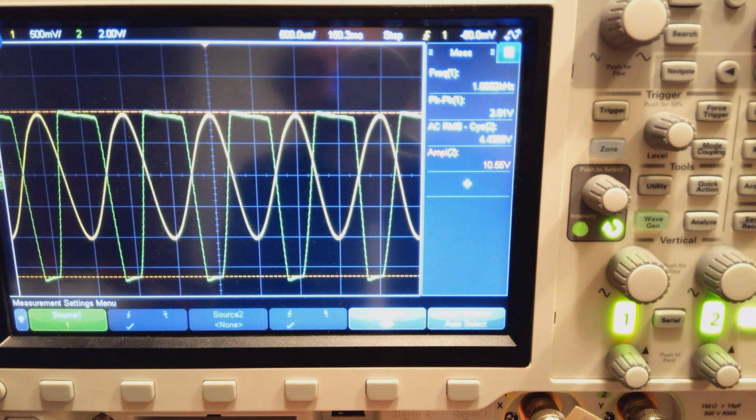If you listen to this on a loudspeaker, you would hear a lot of distortion at this point in time. As you'll learn with Fourier analysis, the sine wave is a single frequency at 1 kilohertz, but now that output is almost like a square wave, and it would have odd harmonics. By overdriving the amplifier here, you've created new frequencies which weren't there in the original signal. We call that total harmonic distortion. So that's about it for this one.